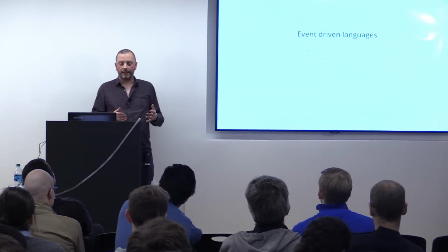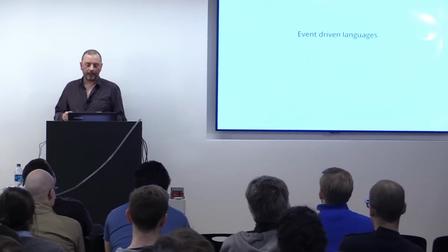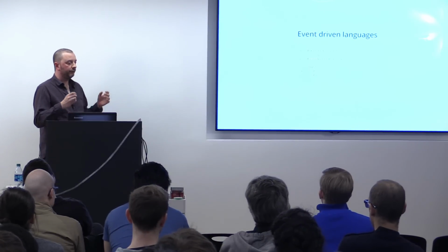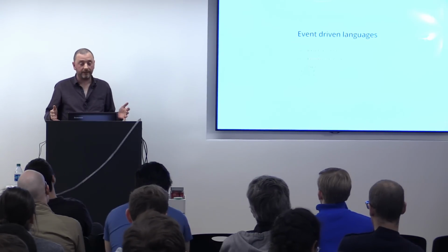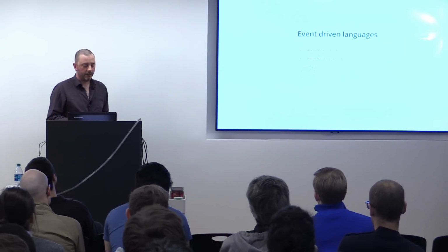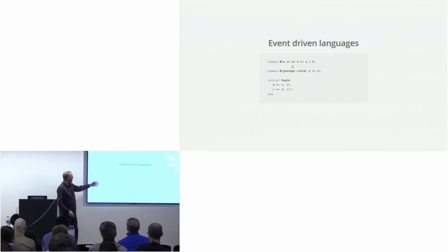Now, an RTL design is a passive thing. It reacts to signals coming into it. And so in order to actually do anything with this within Verilog, you need another language, which is for generating events, generating transitions. So you've got things like this. In particular, it's this #5.